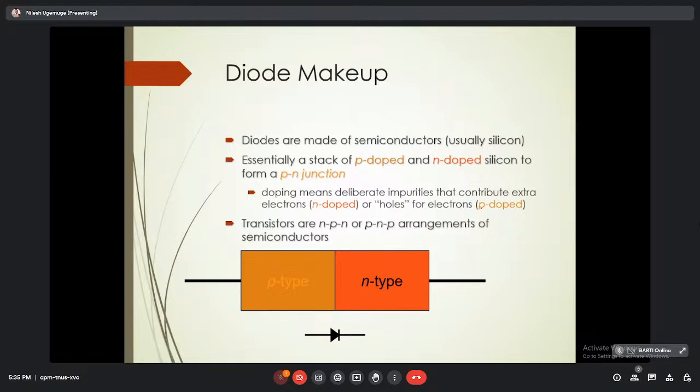And again, when we operate a PN junction diode with forward bias, what will happen? From the p type material the holes will start moving, and from the n type material electrons will start moving, and in between these two a recombination region is formed. Because of this, we get the typical application of the PN junction diode as a rectifier.